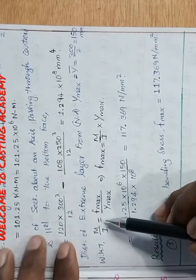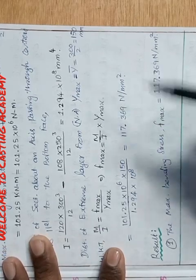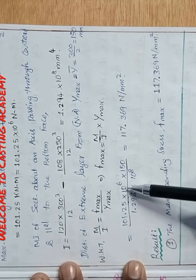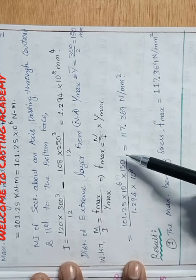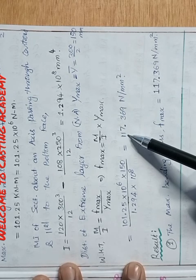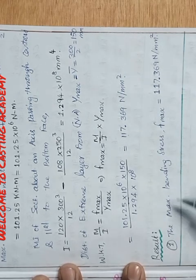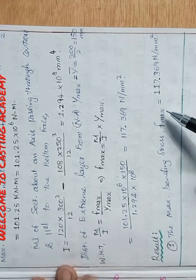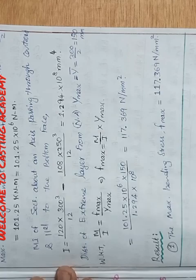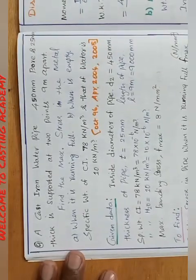We know that M by I equals f max divided by y max. So f max equals M by I into y max. Put the values: M equals 101 into 10 power 6 and y max 150, divided by 1.294 into 10 power 8. We get the answer 117.4 Newton per mm square. The result is that the maximum bending stress occurring in this section equals 117.369 Newton per mm square.